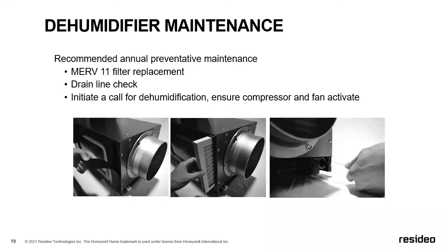Filter replacement, again, we start talking about maintenance, really drain line, you guys do these every day when you're doing maintenance on an HVAC system. Filter, drain line, and then drive the machine on, maybe test our inlet and outlet temperature just to verify that our refrigerant circuit is healthy. But very basic maintenance from a dehumidification perspective. Magnetic door, pull that magnet door off, pull your filter out, replace the filter, and then of course we'll do some drain line maintenance as we do with all of our drain lines.